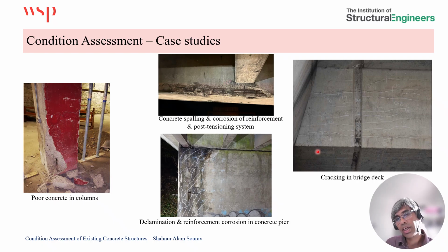This is a photo taken from a bridge that has extensive cracking, and the bridge is a post-tension segmental bridge. You can see the segmental joints, and these are the segments that are connected by the post-tension elements. So there was extensive cracking in this particular bridge, where we proceeded with the recommendation for further crack monitoring.